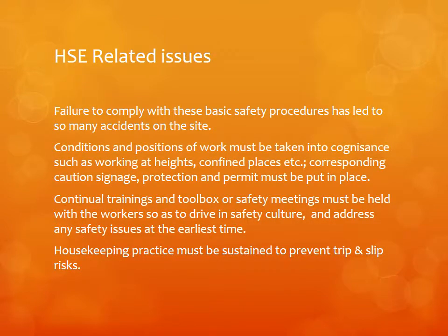Failure to comply with these basic safety procedures has led to so many accidents on the site. Conditions and positions of work must be taken into cognizance, such as working at heights, confined places, etc. Corresponding caution signage, protection, and permits must be put in place.